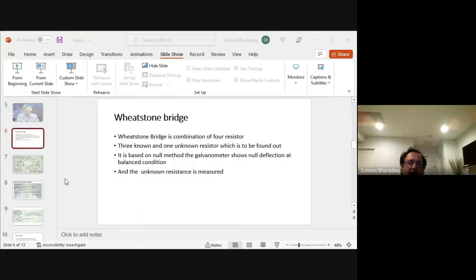Now R prime, in this case, because the current through this one automatically satisfies R1 by R is one, R by R is one. Therefore, there will be no current through R prime. Okay, so this is another classic situation, which is actually a Wheatstone bridge problem.